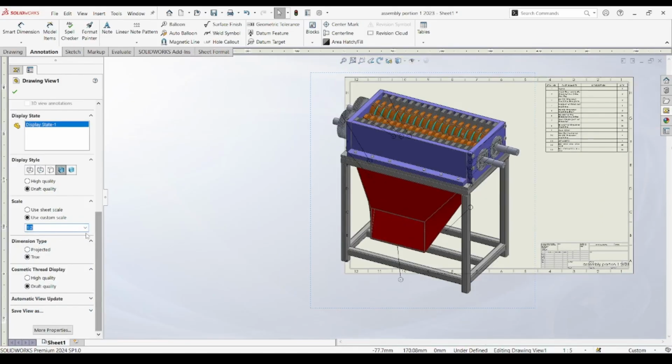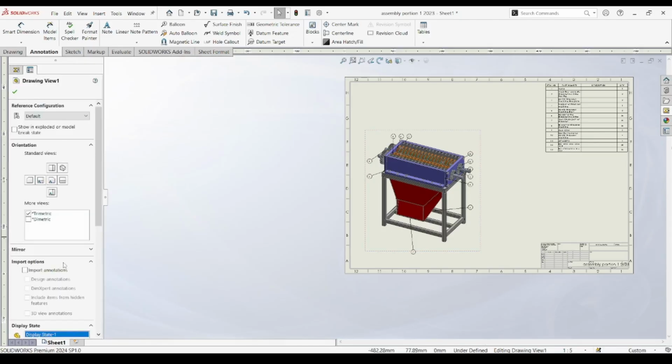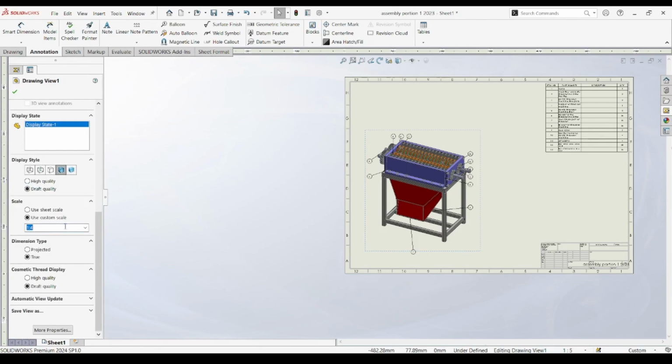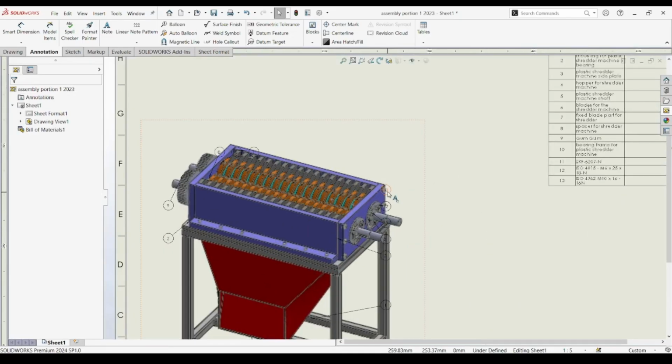We also take a moment to point out common mistakes, like forgetting to include hardware from the SolidWorks design library. In Part 18, we added ISO standard bolts and screws into the assembly, and those show up in the BOM automatically. This reinforces why it's important to fully complete the digital assembly before generating the BOM. Anything left out won't be counted.